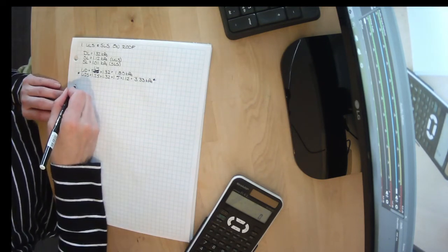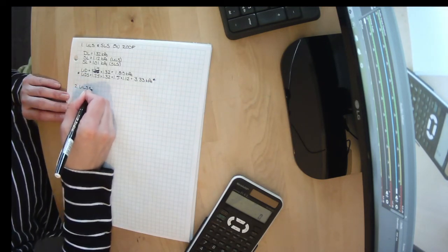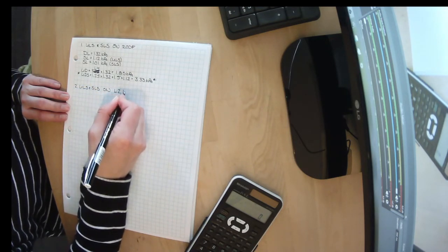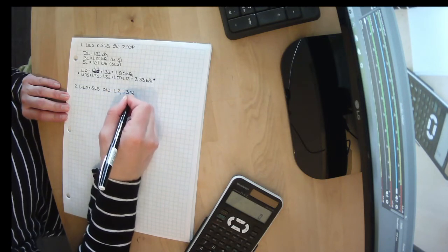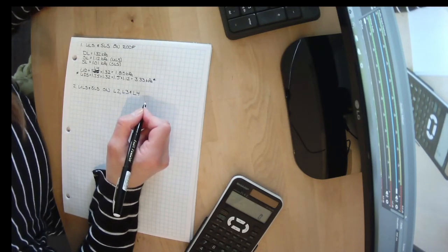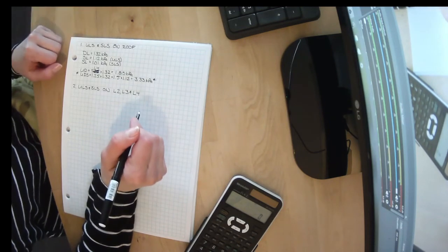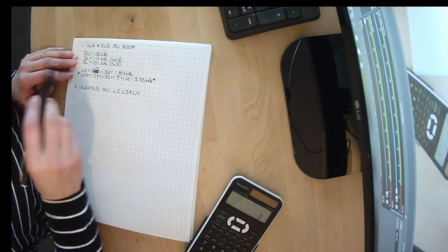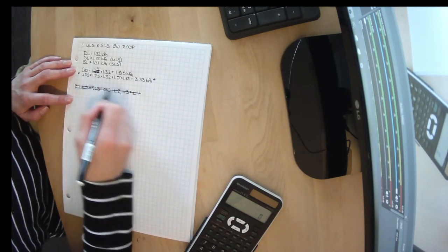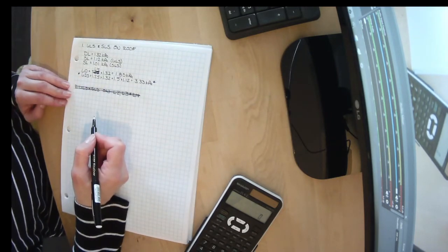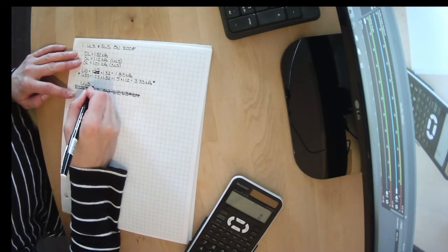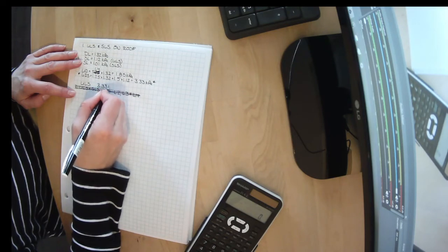The second thing they asked us was to figure out the ULS and the SLS on level 2, level 3, and I believe it was level 4 is how many levels that we had in this building. Well, I forgot something. I haven't figured out the serviceability load cases that I need. So still finishing step 1, this was our ultimate limit states worst case load. So our ultimate limit states load is 3.33 kPa.